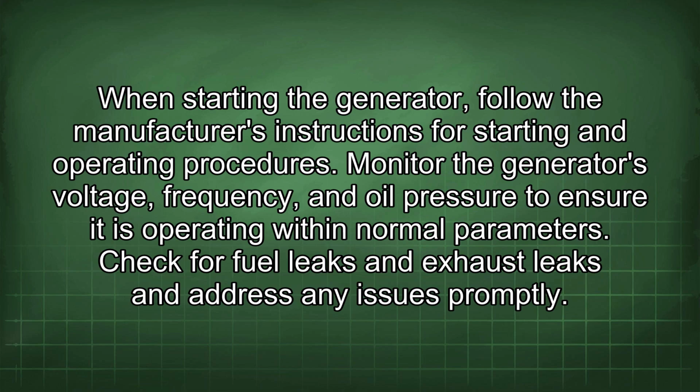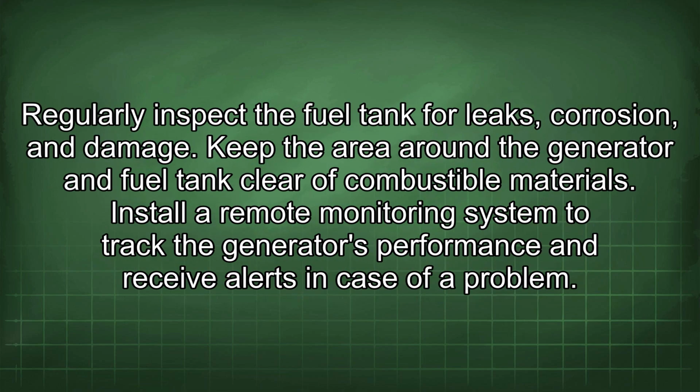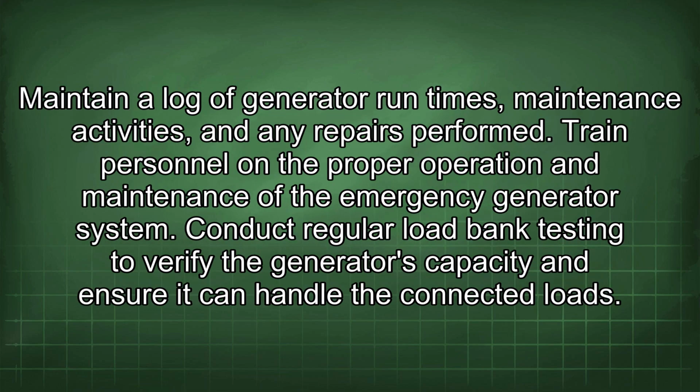Check for fuel leaks and exhaust leaks and address any issues promptly. Regularly inspect the fuel tank for leaks, corrosion, and damage. Keep the area around the generator and fuel tank clear of combustible materials. Install a remote monitoring system to track the generator's performance and receive alerts in case of a problem. Maintain a log of generator run times, maintenance activities, and any repairs performed.